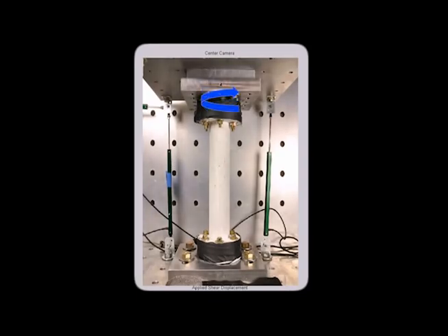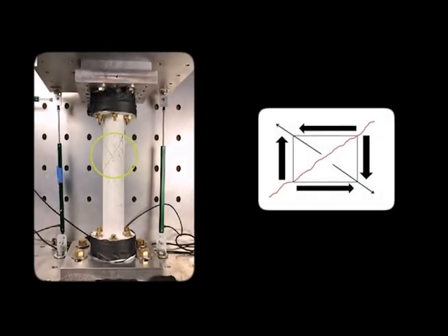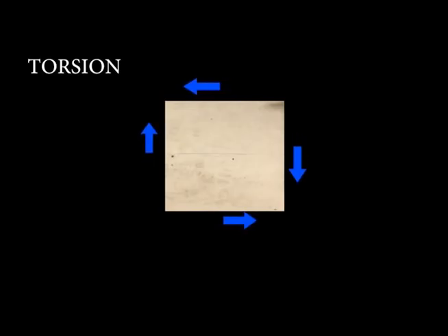Torsion is a twisting action about the longitudinal axis of a member. Since one end is twisted while the other is held fixed, shear cracking and stresses are created in the member due to torsion. By examining a small section of this member, it's easy to see the shear forces acting. If you recall the diagram of the stresses from an applied shear load, they look very much the same as these stresses produced by torsion.